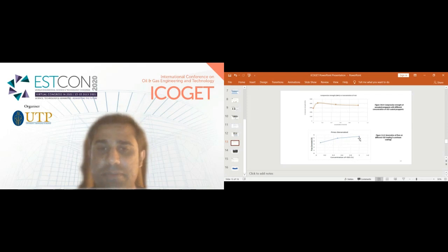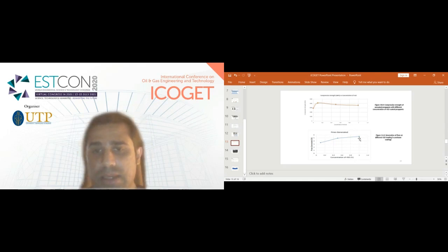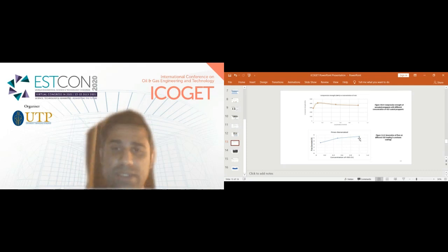So here it is depicted that graphene oxide does not create an effective web-like structure that encapsulates and contains the fines inside the propellant body, and the fines can be easily released from the propellant body. Unlike in the case of CNT, where the CNT was effectively forming a web-like structure and was effectively encapsulating and containing the fines, and the fines were not being released even when the applied load was increased.